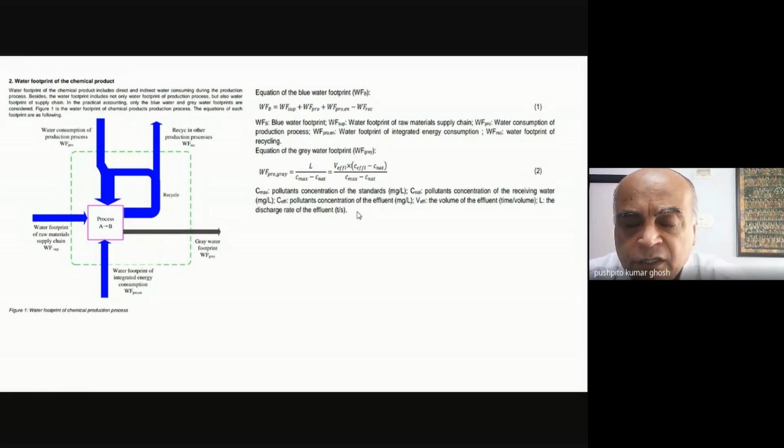Whatever is the critical impurity I have to deal with, I'll have a C max. That is the maximum concentration which I can have. And obviously, if I've got 10 different constituents which are a problem, then I have to go with whichever one is the highest and dilute accordingly. And then totally how much volume of effluent am I generating per ton of process A to B.